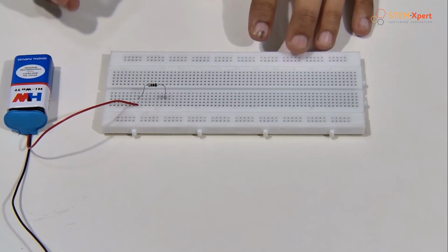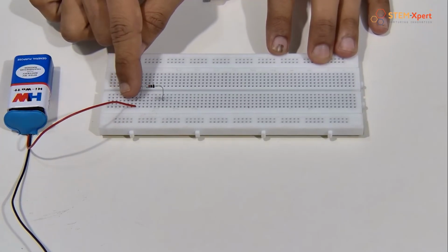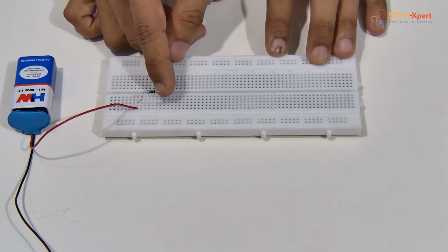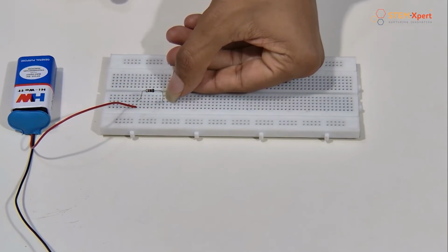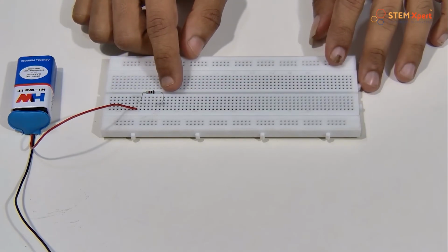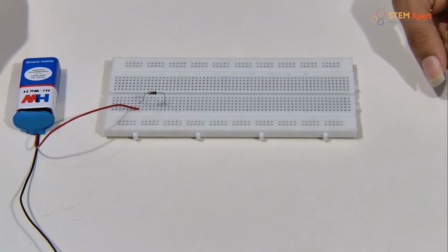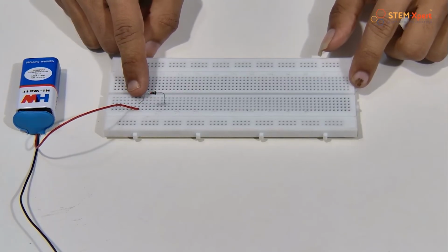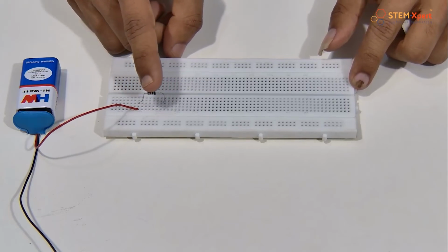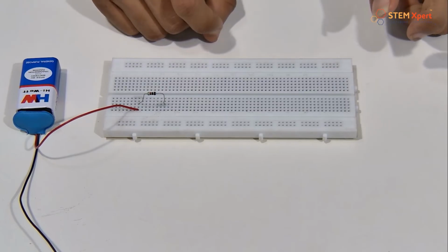So remember our circuit diagram: it starts from the positive of the battery and goes through the resistor of resistance 1 kilo ohm, and finally, as you can see, here is a positive, and at this point we are going to connect our LED. Now your turn, you can also connect your resistor like this. You can start from the positive of our battery connected point and then end at any other point of the B part of the breadboard, not the same point.